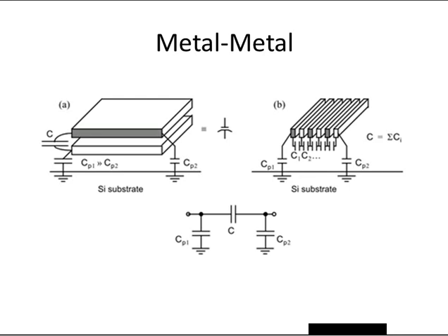For capacitors, the problem may even be in the modeling. You may not be accounting for every fringing field that there is there. So you've always got to allow for quite some variability in these passive component devices. On the other hand, if you're making these passives, again, you're making sets of them out of the exact same unit size devices, what you can rely on is good matching. So matching on the order of 1%, for example, is not unreasonable.